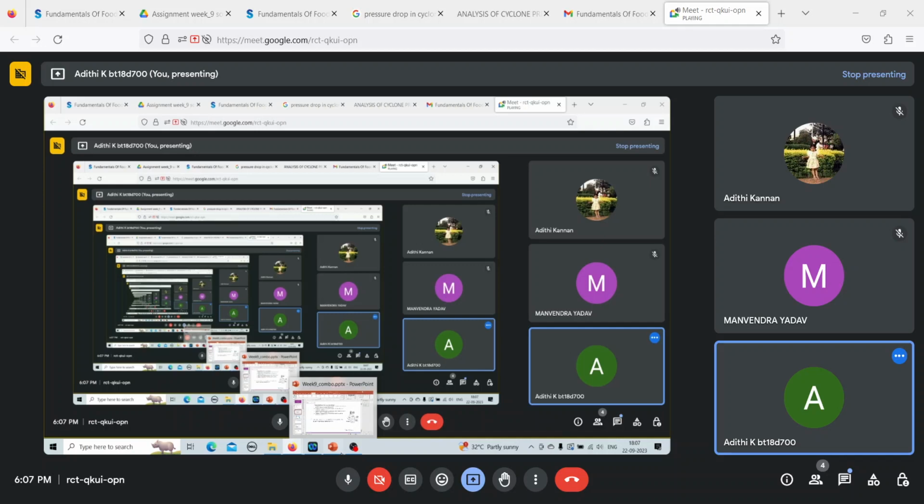And what is alpha here? What we mean by cake resistance is that it is derived from something known as the Karman-Kozeny equation, which is described in the video lectures. So in the Karman-Kozeny equation, you're looking at the specific cake resistance, because now it's very similar to that of a fluidized bed, where you have particles and then your fluid flows between these particles.